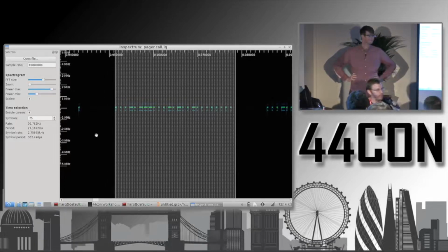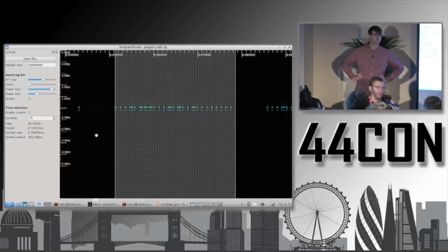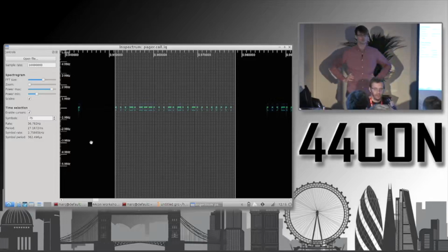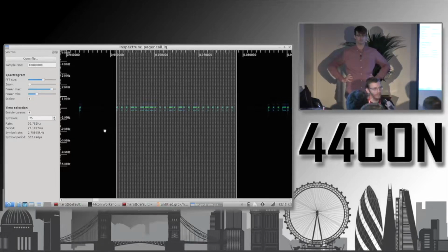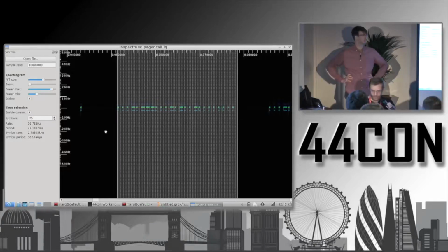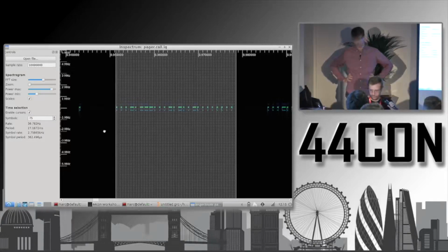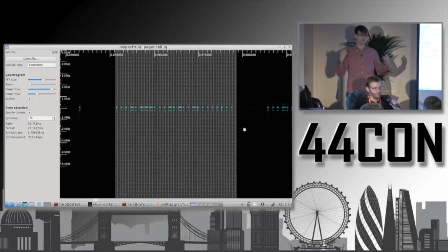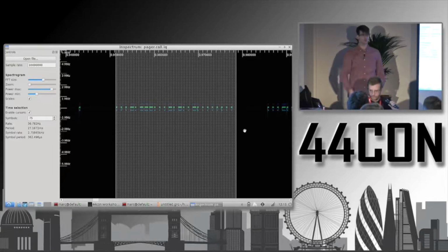So is everybody getting closer to set up with the RTL SDR on GNU Radio? I think it might be good once we have anybody who wants to get set up, we can start setting up this page a little bit more and make sure that you all can see this data on your laptops. Yeah, so once we get all the rest of these USBs flashed, we'll go back and we'll send some signals out. We'll help everybody get set up with a GRC file flow graph to capture the waveform, and then we'll help you visualize it and start reproducing this on your own system as well.